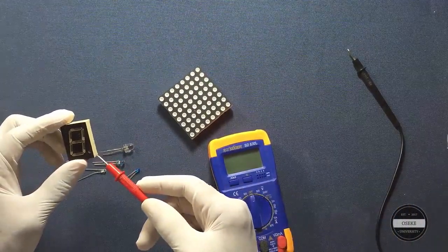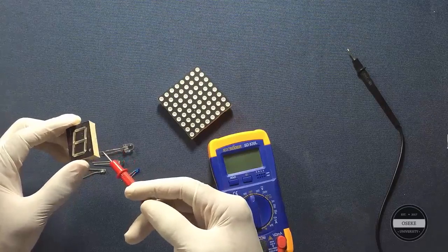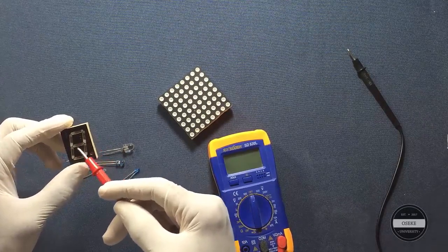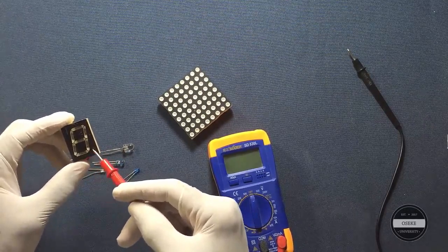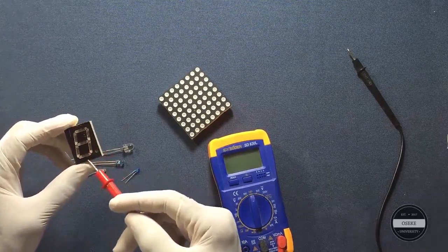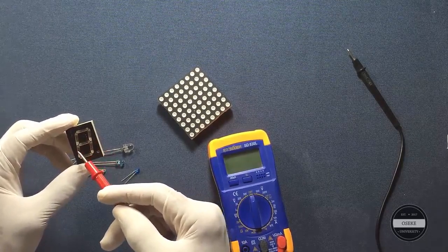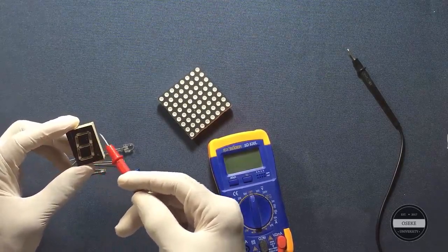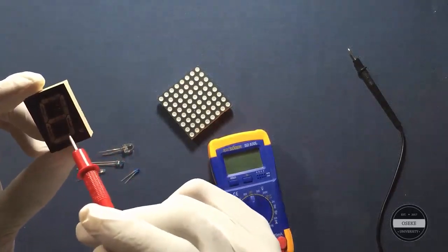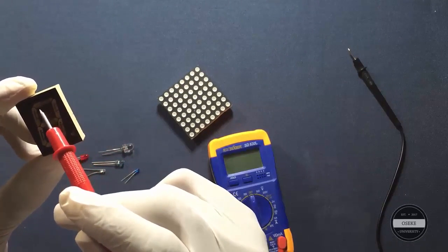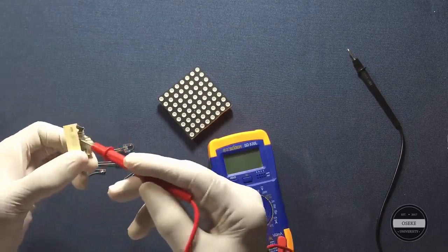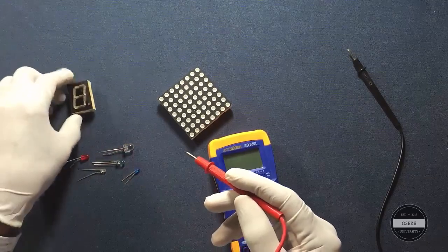This is a 7-segment LED display. Why they call it 7-segment LED is because it actually has 1, 2, 3, 4, 5, 6, 7 segments. Now this one has 8, but many of them have 7. Each of these 7 segments is made up of LEDs. If you look closely, you will see the LEDs inside. This one has multiple LEDs, so each of these segments can emit different colors. All right, and there are pins here that you use in connecting the 7 segments to your circuit.